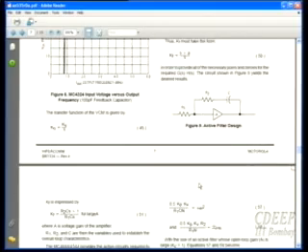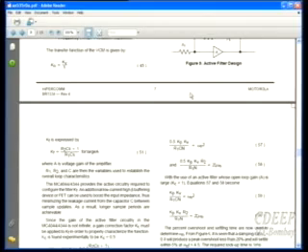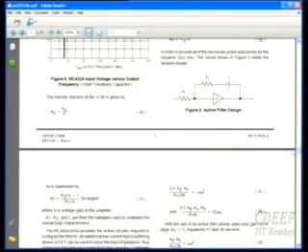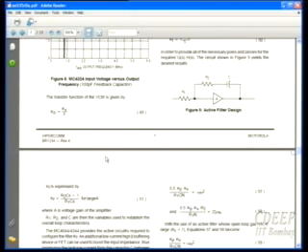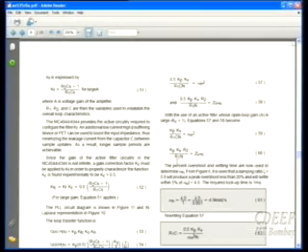It has a zero, and if gain is very high, it has a pole at S equal to 0. Because when gain is very high, means A is very high, at low frequencies this path is open, and whatever signal you have will get multiplied by A and come to the output. If A is large, then almost at zero frequency you will have a very large gain, means you will have a pole. Therefore, effectively, it's not S0, it's R1CS plus something, but that is negligible. So it is effectively the same transfer function that we implement using charge pump by putting an RC.